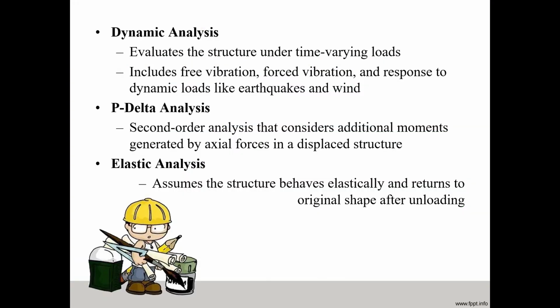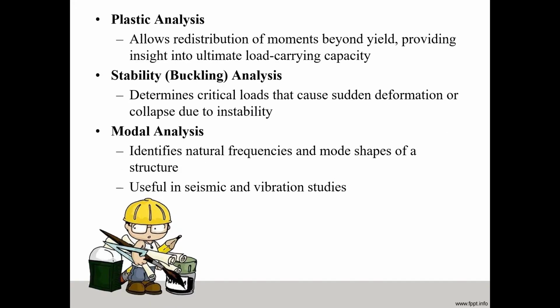Then P-delta analysis, which is a second order analysis that considers the additional moment generated by axial force in a displaced structure. Then elastic analysis assumes the structure behaves elastically and returns to its original shape after unloading. Then the next is plastic analysis. Plastic analysis allows redistribution of moment beyond yield and provides insight into the ultimate load carrying capacity.